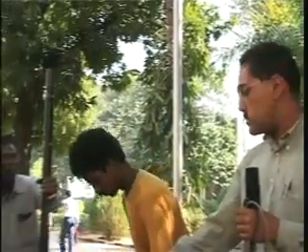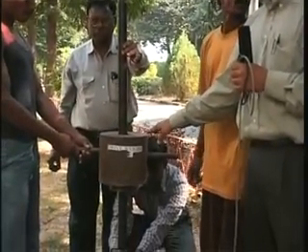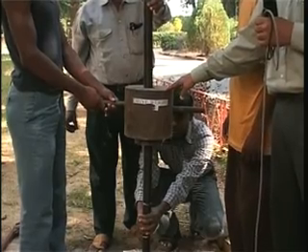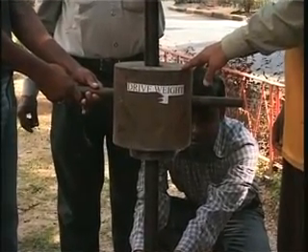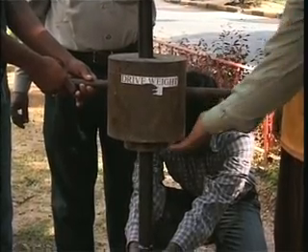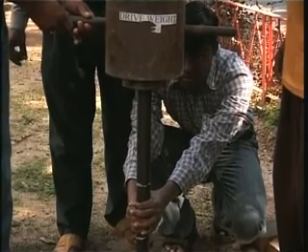Okay, so now we have got the setup into the ground, and what we have got here is a standard SPT hammer mounted on the SPT rod. This is a hammer called a donut hammer. This hammer has got a weight of 65 kg. It is going to fall through 750 millimeters onto the anvil here, which is underneath the hammer, which may not be visible from where the camera is.